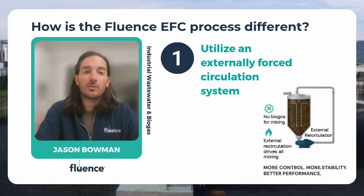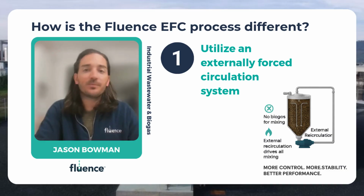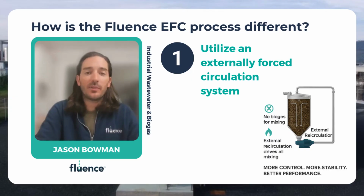In more conventional high-rate granular systems that act as a gas mix system, these systems can experience swings in mixing intensity and internal velocities as the biogas production goes up and down with incoming loading. This can lead to poor granular separation. In other words, a less expanded granular bed with all sizes and densities mixed together inside of the reactor. Now, one may think that this is a good thing, but keep in mind that we're trying to maintain specific, larger, more dense granules in the core of the reactor.